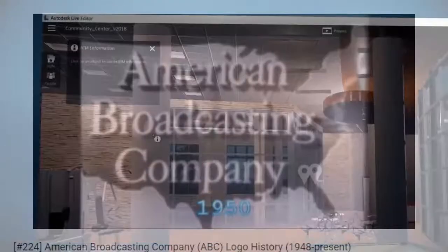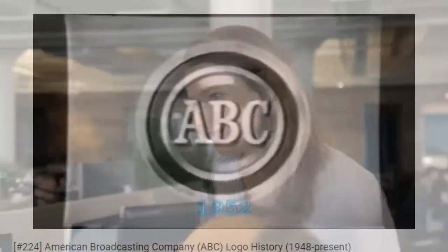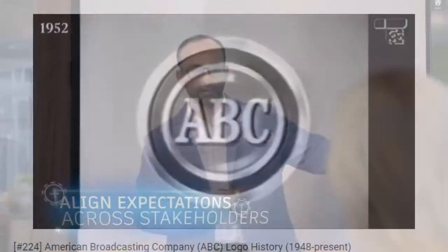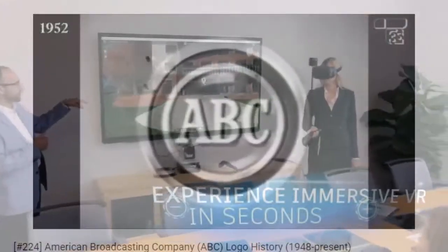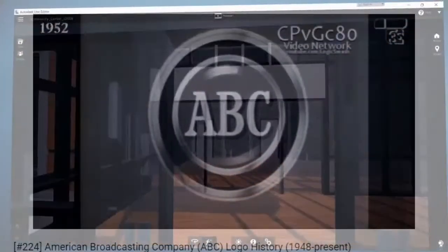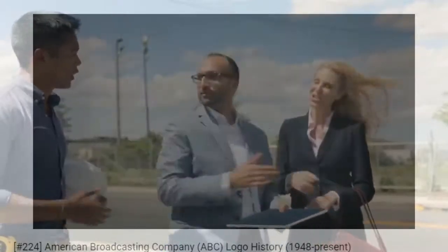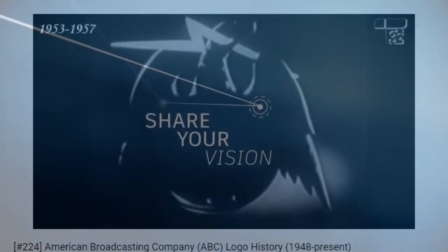Begin a new in-place component by going to the Architecture tab and selecting Component Model in Place in the Build panel. Set the family category to Floors and specify the name as Floor Edge Level 1. You are now in the Family Editing mode, and the ribbon will have different tabs and panels. Click the Create tab and select Void Forms, Void Sweep from the Forms panel. Click the Pick Path tool from the Sweep panel and choose all 4 top edges of the perimeter of the floor at level 1. You can activate the 3D view floors only to complete the picking of all 4 edges as shown in Figure 13.